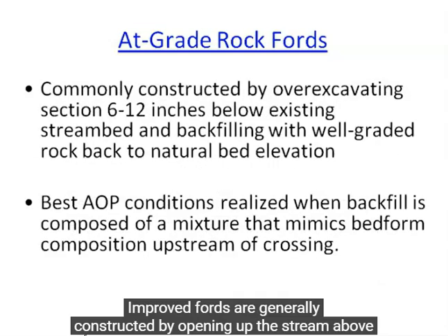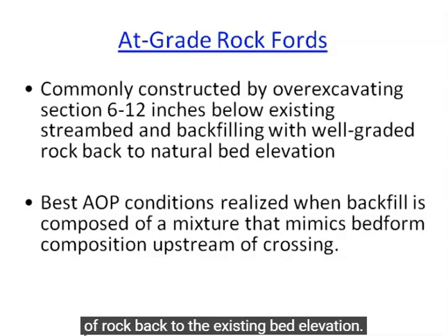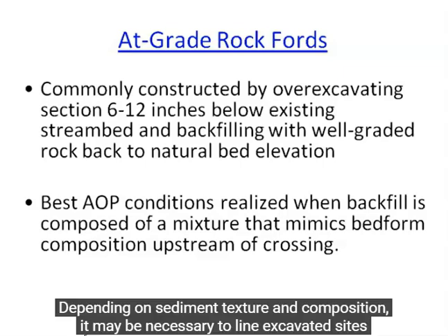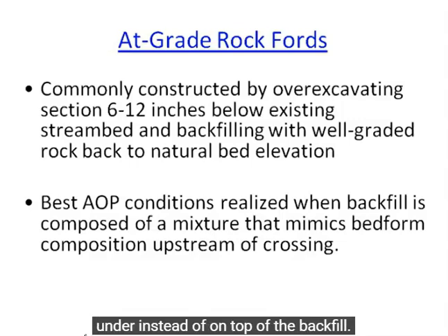Improved fords are generally constructed by opening up the stream above or atop a natural control and backfilling the cut with a well-graded mix of rock back to the existing bed elevation. Sometimes it's necessary to augment or improve the natural control with larger material. Depending on sediment texture and composition, it may be necessary to line excavated sites with geotextile to control seepage or cut off subsurface flow that might flow under instead of on top of the backfill.